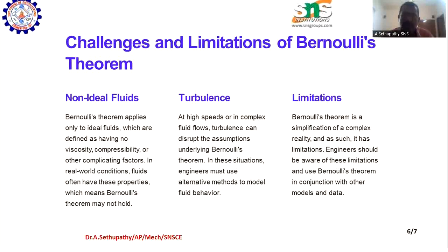What are the challenges and limitations of Bernoulli's theorem? Non-ideal fluids: Bernoulli's theorem applies only to ideal fluids, which are defined as having no viscosity, compressibility, or other complicating factors found in real world conditions. Fluids often have